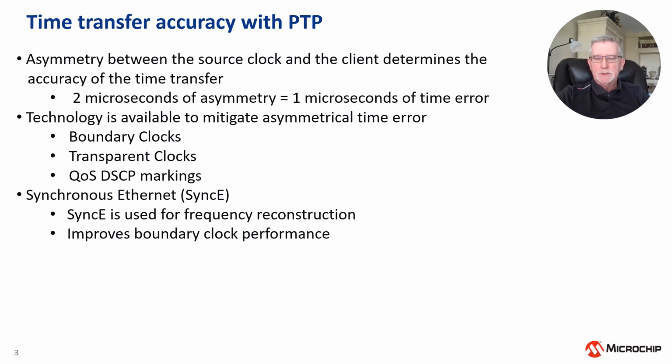So there are limitations to PTP, where whatever we can get the asymmetry down to, we can correct to half of that. So that's how the PTP protocol works, and we can improve the performance by eliminating some time error in the network, by eliminating the time error or asymmetrical time error of some of the devices in the path between the receiver grandmaster function and the client itself.